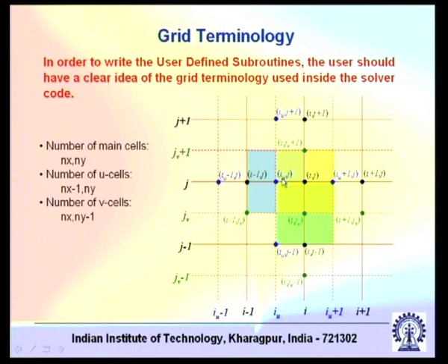In this particular figure, wherever you have I with subscript u, that indicates the index where you are solving the x momentum, u momentum equation. Similarly j with index v will indicate that you are trying to solve for the y momentum equation. So I index for x momentum and j index for y momentum, and in this particular example we are using certain nomenclature, so it may be better to introduce that.